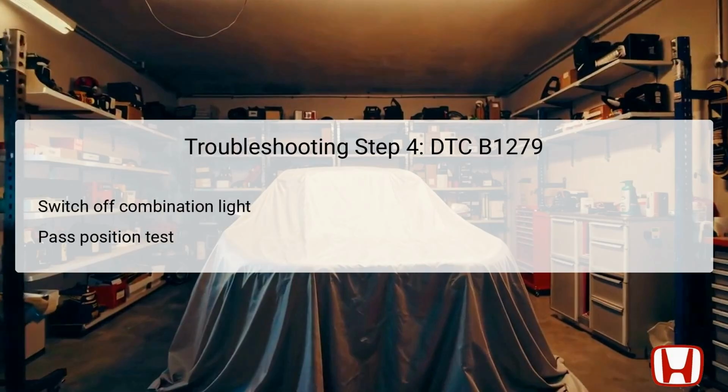Following the previous checks, you will turn the combination light switch off and then to the passing position. This operation simulates a real-world driving condition where the driver might need to indicate briefly without switching on full beams. It is important for assessing whether the dimmer switch can operate correctly across different positions of the combination switch.